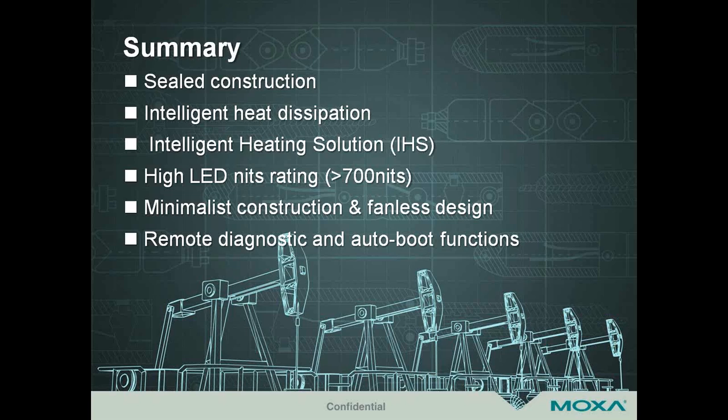Well, it's a complex question. The associated location or the associated apparatus is a bit confusing. You can tether an HMI, or in this case an intelligent HMI or panel PC, to a lot of operations. So it all depends on the operator's use of the panel PC. They could be controlling a drilling rig, for example, a land-based drilling rig. It can be inserted into a dashboard of sorts, so it can be regarded as an embedded system. And in that case, the full unit being IP66 regulated might not even be a necessity. It could only be applicable to the actual front panel and screen. So that's one answer for that scenario.